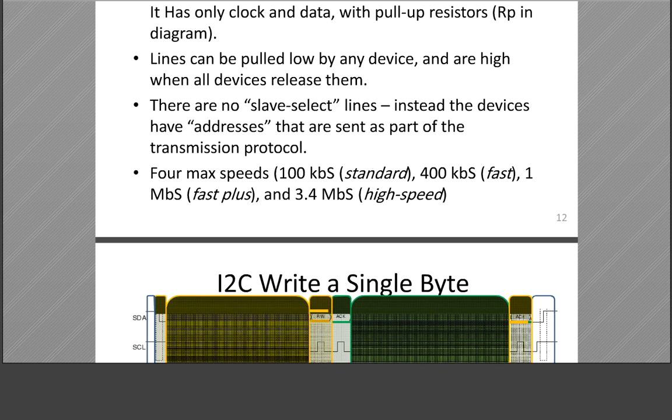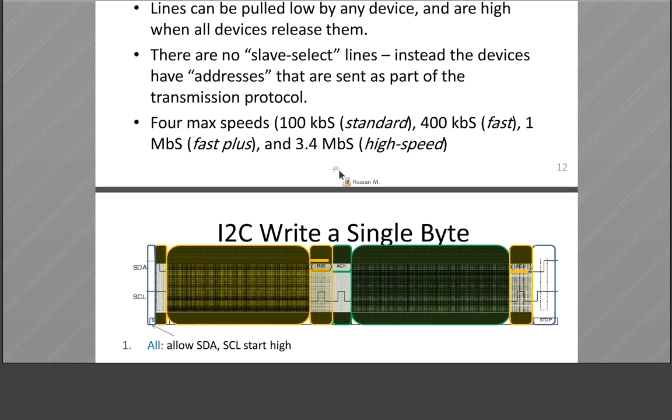When a packet is shared over the common bus, each slave whose address is the same as the packet address acknowledges to the master, and a session starts. Some speeds: 100 kilobit per second in standard, 400 kilobit per second in fast mode, 1 megabit per second for fast plus, and higher speeds, etc. I2C is a live protocol, and they are improving it.